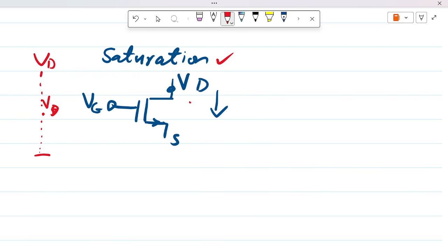let me put in values here. So let's assume the VTH is giving us 0.4 volts. This depends on the wafer that the device is being fabricated on, and the drain voltage is 1.0 volt and the gate voltage is 0.8 volt.